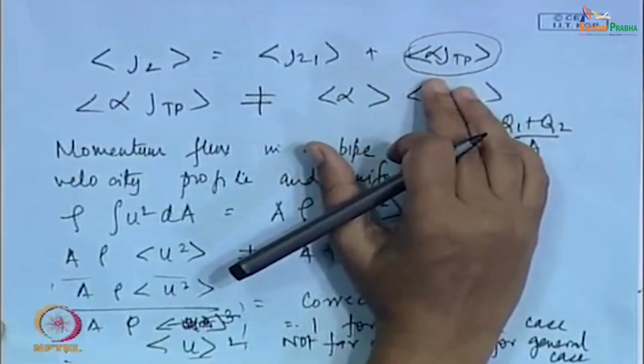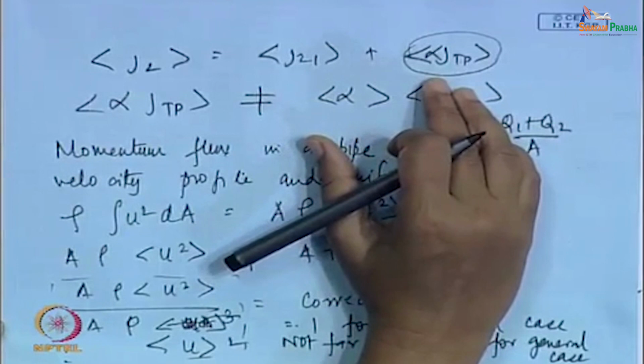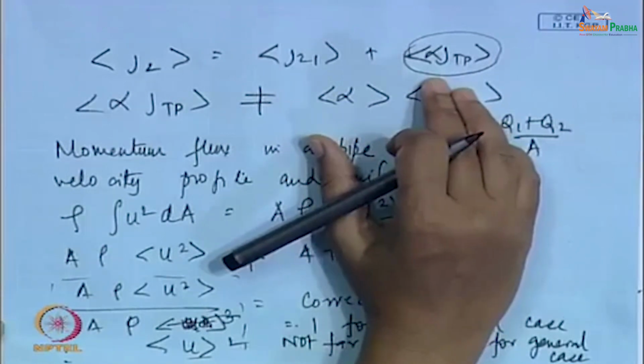This creates a problem. Now, this is a product of two quantities which might vary across the cross section. So, therefore, what has to be done? The volumetric concentration has to be measured at each and every point, your overall volumetric flux has to be measured at each and every point, then the product has to be made and then it has to be integrated. For engineering applications, this is very, very difficult.